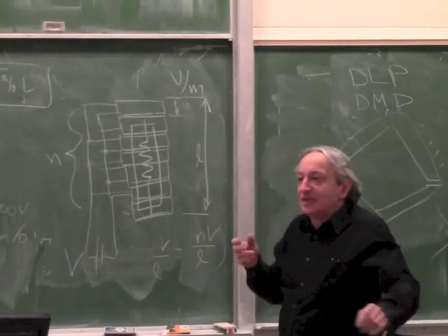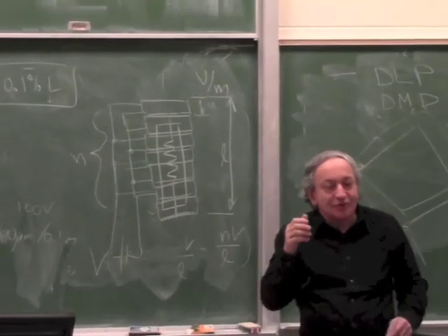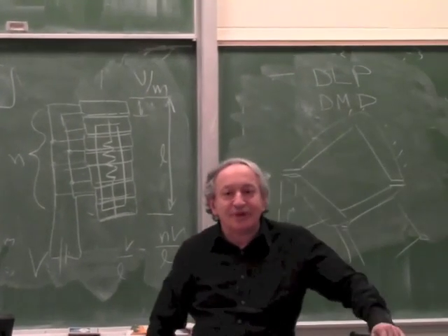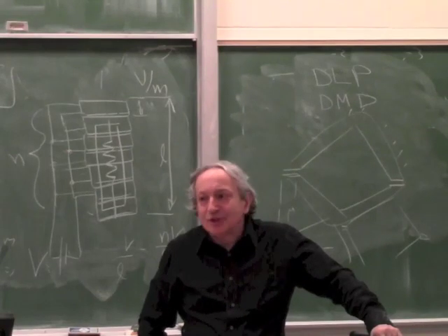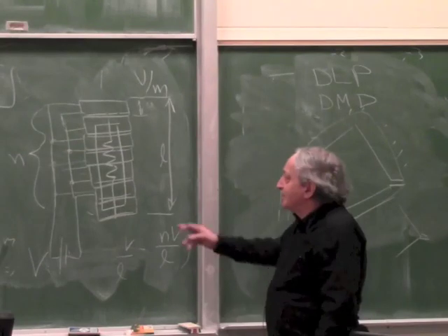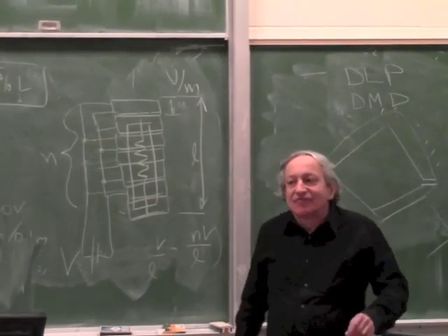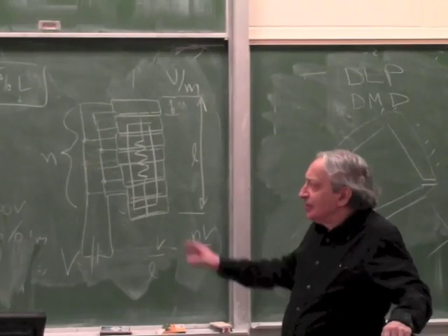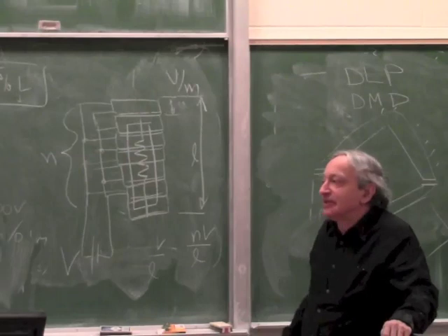You give it a voltage, watch the strain gauge to see how much it moved, and close the loop to force it to move 55 micron. Okay, so the commercial piezo actuators, the ones which are accurate, have a built-in strain gauge to close the loop. I know I went a bit fast here, but we'll do a quick refresher on Thursday.